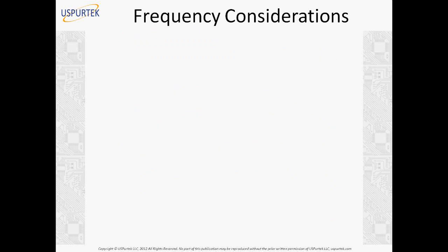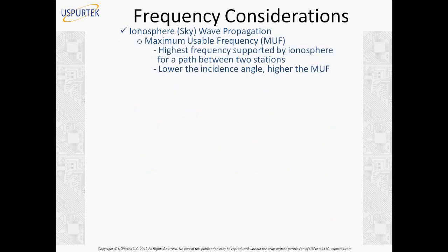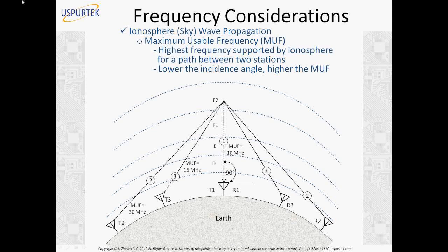Now you might wonder why I'm explaining all these terms. Slowly we'll see. As an operator of skywave propagation, what do you have to worry about? You have to worry about the maximum usable frequency. What is the maximum frequency I can use within the 3 to 30 megahertz band? Why do I need to know that? Because the properties of skywave propagation are changing all the time, with time of day, with season, with solar activity, and so on. And also with elevation angle.